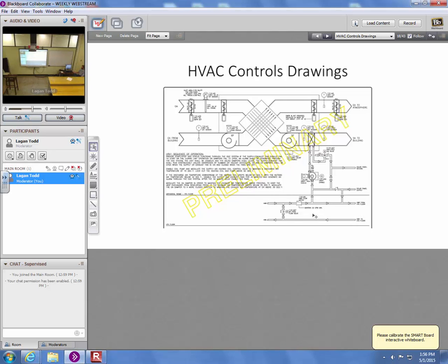But for troubleshooting, whether it's new construction or existing systems, it's very important to try to gather as much of this kind of information as you can get your hands on. You can walk up to an HVAC system, and this is more true the more complicated they get, and you can observe it operating, and you can start to get a sense of what the current sequence of operation is as you've observed it. But then to try to make an assessment of whether that's the right sequence or the best sequence can be difficult.